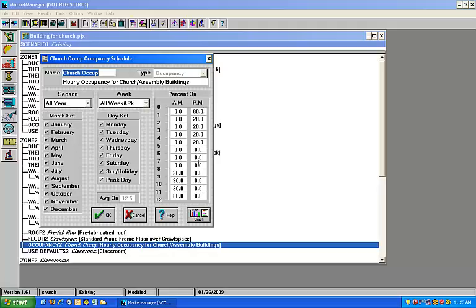Okay. Now, the only reason they care about that is the occupants will create heat. And so when you have more occupants, you have more air conditioning and less heating requirements. It does not do CO2. You can't use this for demand control ventilation.